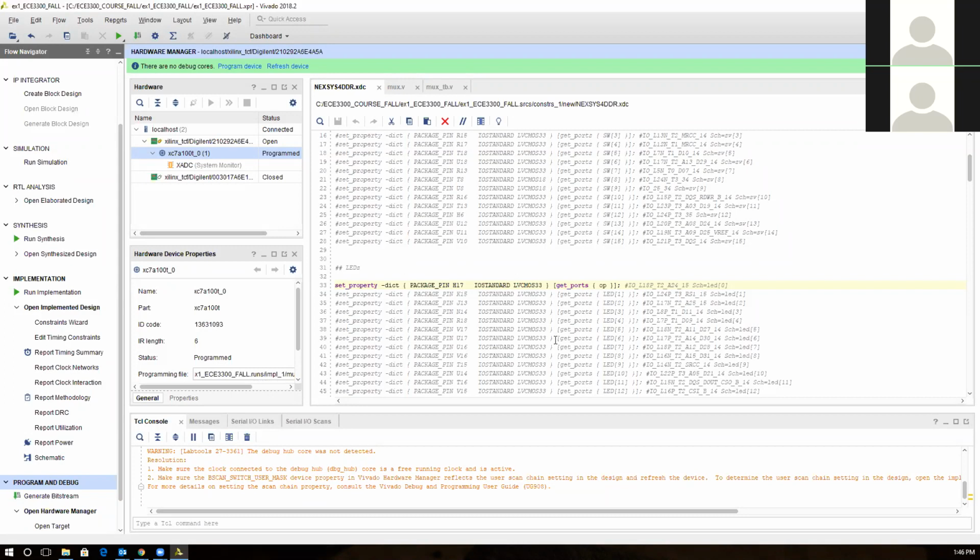So if I push X with 1 and I push Y with 0 and select 0, nothing of this LED will be turning on. Do you agree? But if I push the select on, so I selected X in this case, and the LED turned on. If I flip X to be 0 and Y is 0 and select is 1, nothing is coming out unless I push select with 0, which is proving that the test bench did a great job and the realization in the board is matching what I tested.